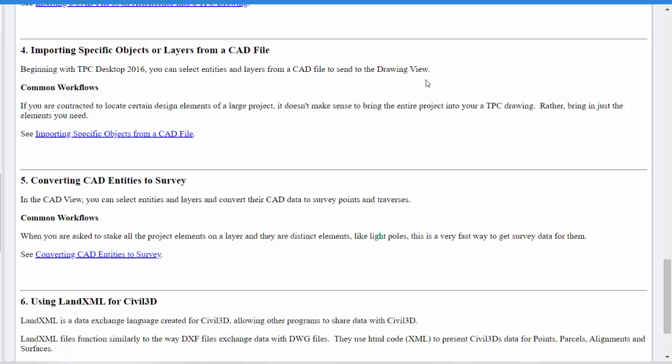The next revision that comes, just create a new drawing in Traverse PC, go to that same layer, import that layer over to your drawing, do your markup, and write a PDF file out if that's what your deliverable is, and save that as the revision 2 drawing. So you could actually keep the copies of all your revisions as drawings inside of the Traverse PC survey. That's just one way. I mean, that's what this whole webinar is about, is kind of introduce different ways we can tackle this. So let's just take a look at this workflow.